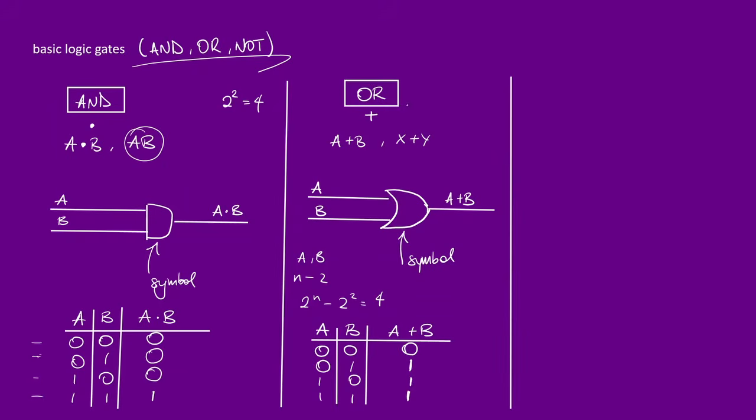And the last thing we're going to look at is the simplest guy in the group, and it's called the NOT gate. So what is the NOT gate? The NOT gate has a couple of symbols for representing it. So let's say we've got a binary variable C, and I wanted to express not C. I could express it with a bar, or I could express it with an apostrophe. Both of these are valid ways of expressing not C. It's important to note that the NOT gate takes only one input and gives out only one output.